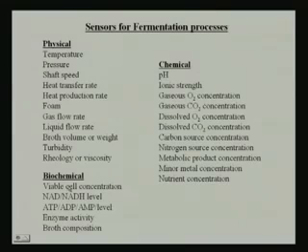When we are going for the biochemical sensor, we are talking about the viable cell concentration. This is one of the very important parameters as far as the biological product is concerned. Suppose we have inoculated our reactor system with the inoculum, but we do not know what the percentage of living cells and dead cells is. If the percentage of dead cells is present, that is the waste. It does not have any role in the product formation.